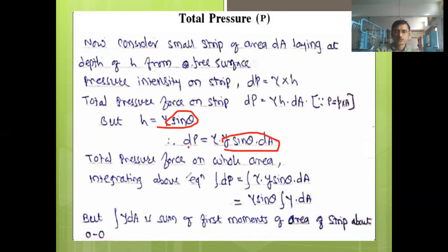Total pressure force on the whole area: integrating the above equation, we get gamma sin theta into the integration of y dA. But this y dA is nothing but the sum of the moment of area.